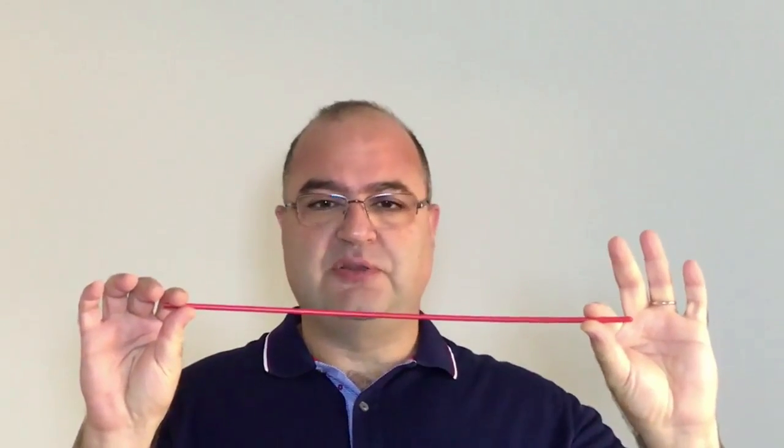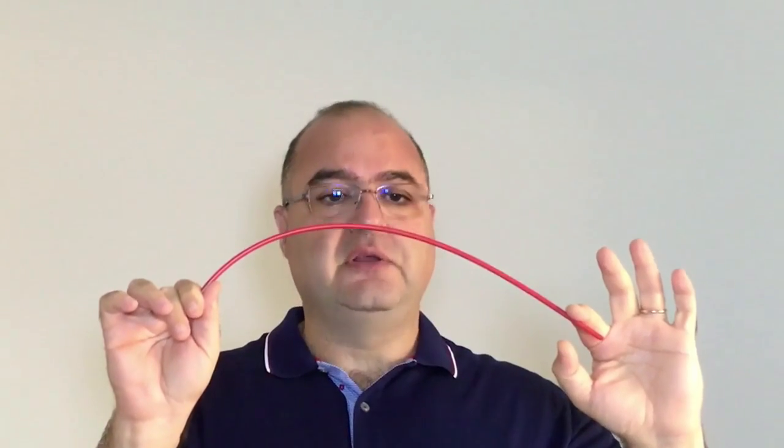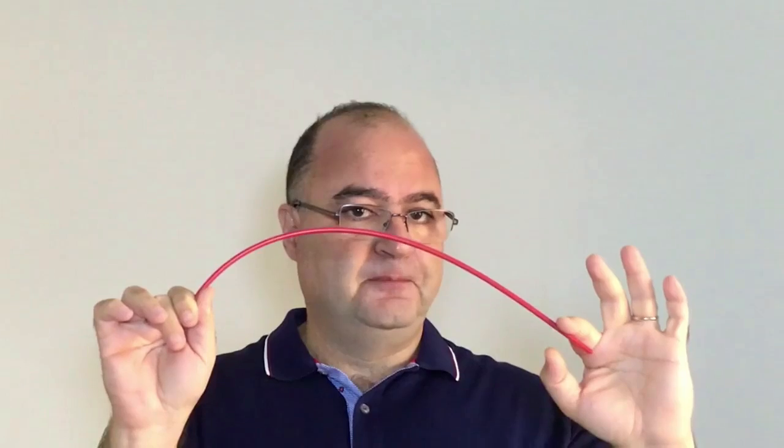This means there are hinges at both ends and we apply a moment at one end. This straw shows the deformed shape. This shape would be about the same for a steel, concrete, or wood beam, but of course with much smaller deformations. Those deformations are usually so small that they cannot be discerned visually without magnification or without sensitive cameras.